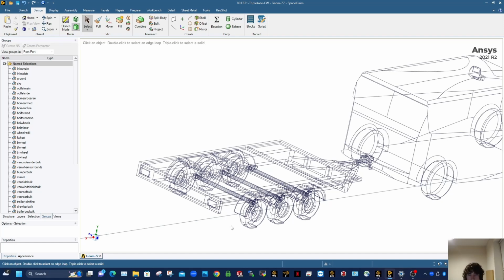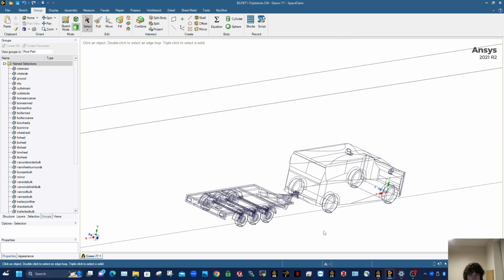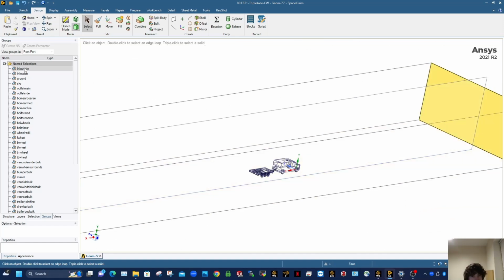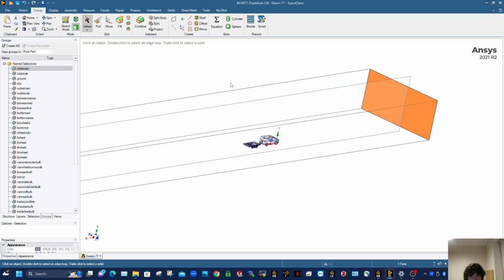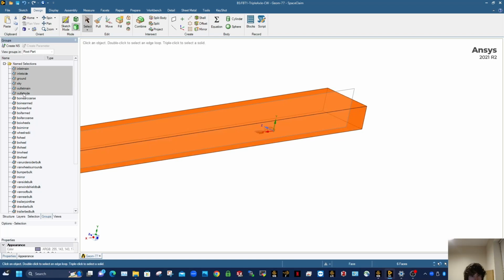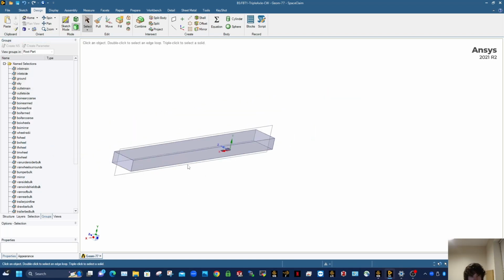So it's just something to try and avoid if you can. That detect can help do it. Now, that's done. What we're going to do next is change the domain size, and then we'll add in the new body of influence for the crosswind. So we'll show the faces there, the outer faces.